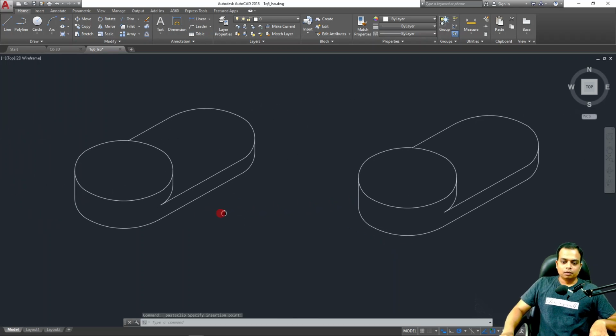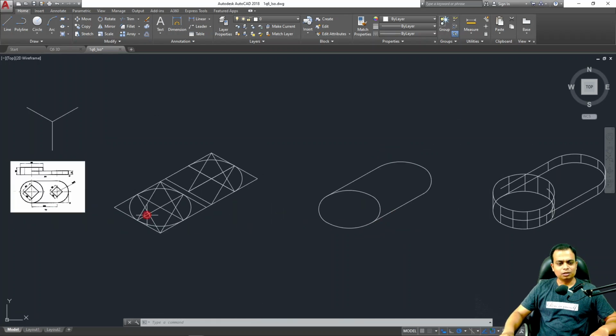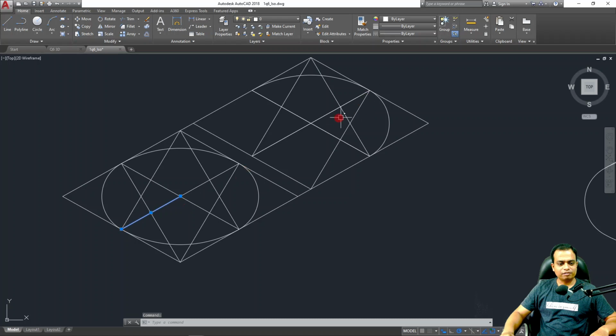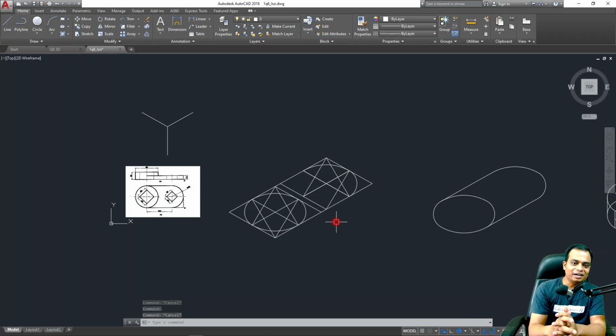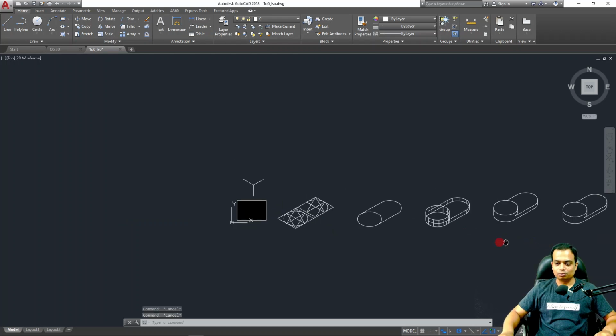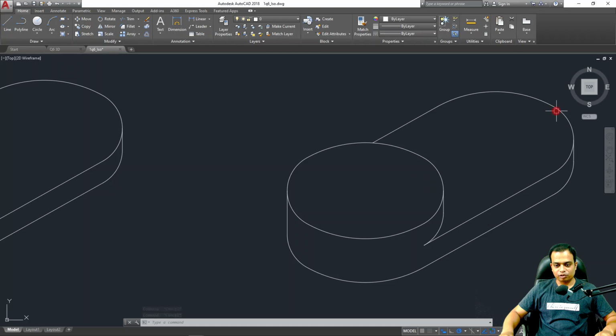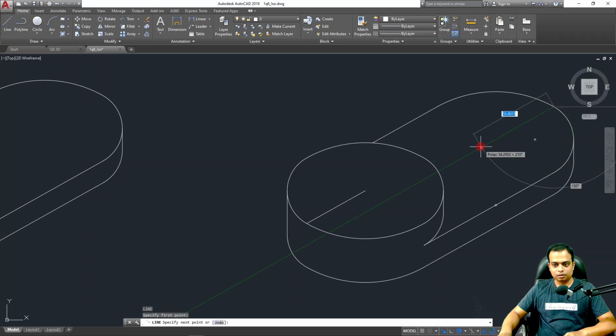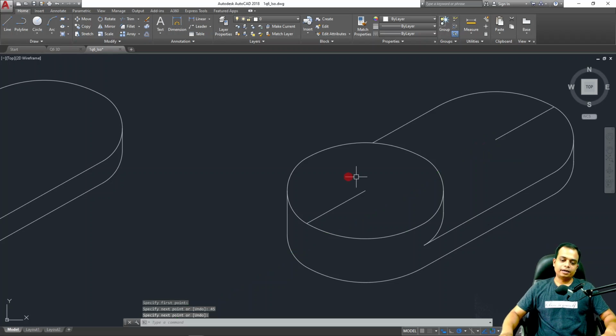Okay. If you watch, you sort of know this. This is 45 from the left, 45 from the right. Again, you already have this point, right? In the construction, this is the point you have. So you guys may get into trouble if you don't do your work with a lighter pencil. Make sure that you follow all the instructions carefully. So 45 from over here and 45 from over here. Let me demonstrate. 45 from this side, enter, and again 45 from this side. Where is that point?